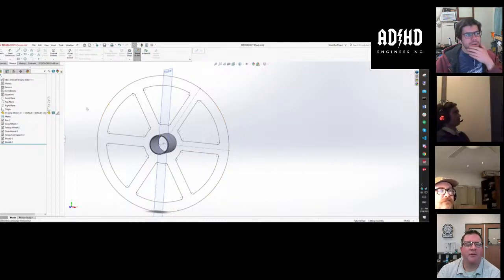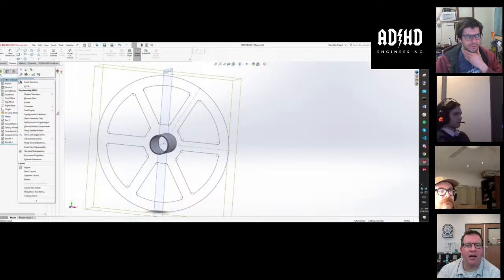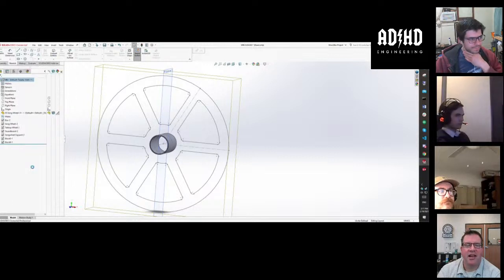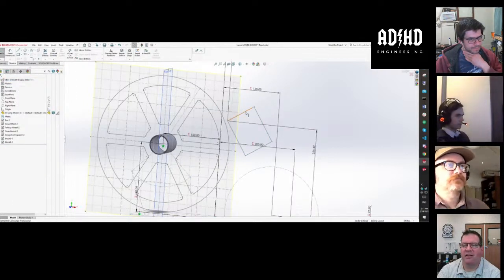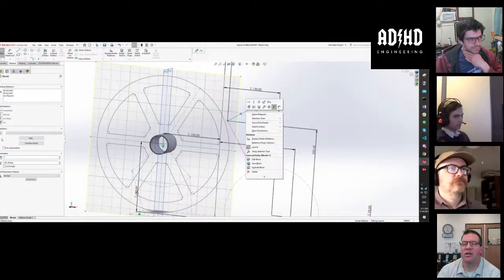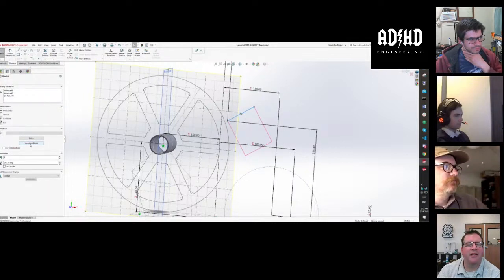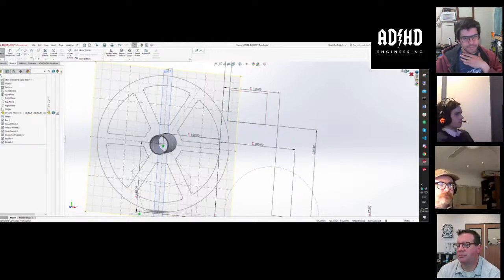I ran into that same thing. If you can edit the properties, right click on the block instance, and go to insertion point, and then it'll give you an insertion angle as well. There you go. Look down there, properties. 302 something degrees. Yeah, there you go. Lock your angle. Great. Sweet. Well, that's useful.